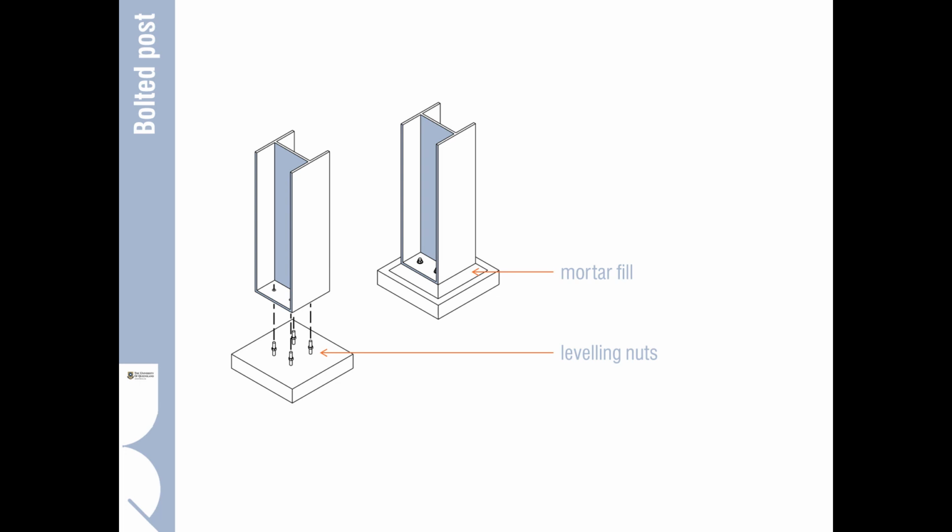Now here we can see a typical heavy steel post coming down onto a concrete either mass footing or slab. Now one of the typical problems with steel connections to imprecise systems such as concrete and so on is that steel is always quite precise, quite small tolerances, whereas the set out of things like the studs in or the starter bars in concrete is a very imprecise system. So we do need to make tolerance so that the two systems come together well.